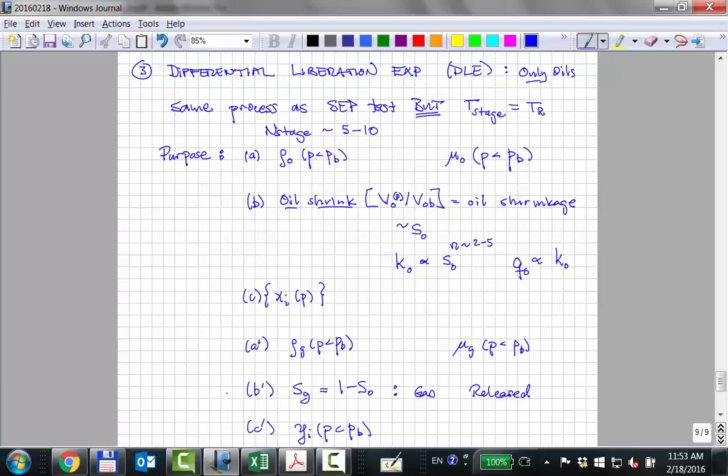So this gas release will not be equal to the gas release we have at the separator. No, it's the gas released in the reservoir. You want to know the gas released in the reservoir, basically. Yeah. Now, some of that will make its way to the surface, but it's really looking at how much gas comes out of solution, how many moles of gas come out of solution. And if you know the moles that come out, you know the gas density, and you know the gas molecular weight or composition, then you know basically the volume of the gas but at reservoir conditions.